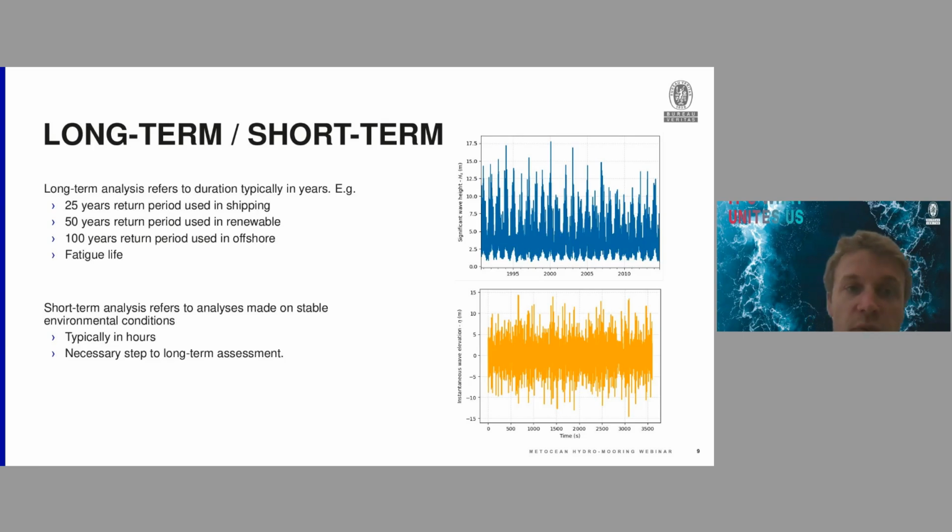Then a bit of vocabulary when designing a floating unit. There are the terms long-term analysis and short-term analysis, and here I want to specify a bit more what they mean. When we say long-term, it refers to durations that are typically in years. For instance, in shipping, we design with a 25 years return period. In renewables, it's more the 50 years, and in offshore, we also have the 100 years, which is quite standard. And the fatigue life is also something which is typically comparable.